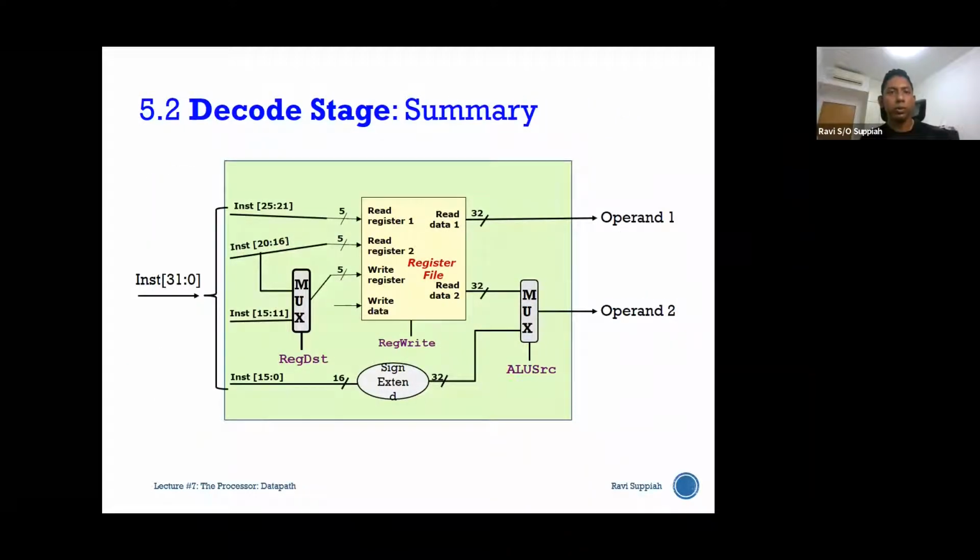So this is where we stopped, the decode stage of your system. In the current design, we can see that it supports our R type, our I type, and our branch instructions well, no issues. Another thing we talked about just now is that there will be operations carried out by different parts of the hardware that are not actually used in that particular instruction, but are still done anyway.